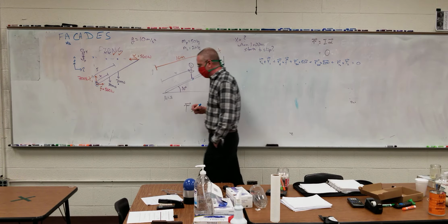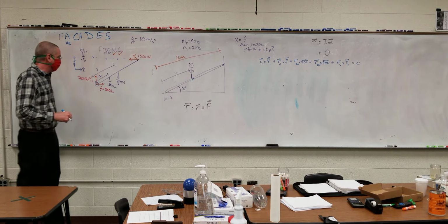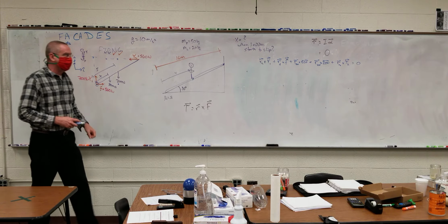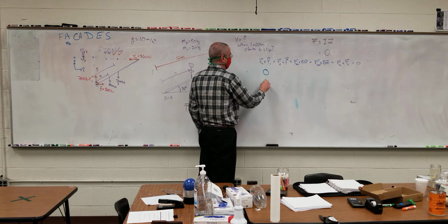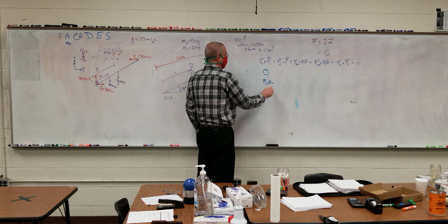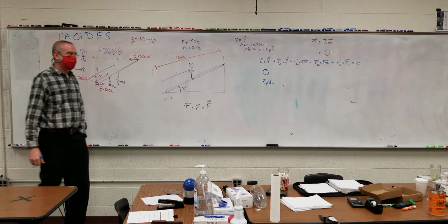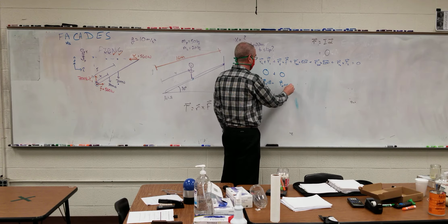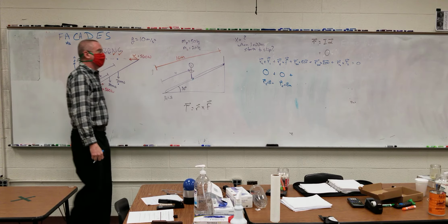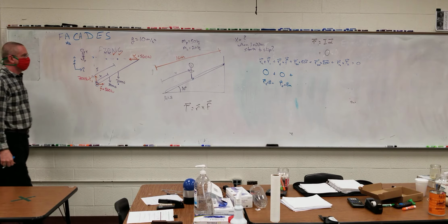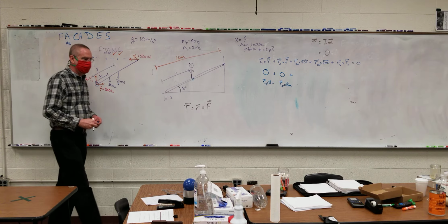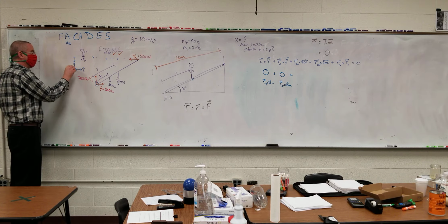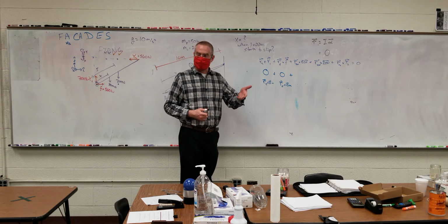And again, this R vector, the moment arm, is a vector from my pivot point to where the forces are applied. So here's my pivot point, and R Y1 is 0 because this force goes straight through it. That's 0 because R Y1 equals 0. Plus 0 because the moment arm from the pivot point to the friction is 0. So we set up our coordinate system with i hat, j hat like this. K hat is coming out of the board. We did an i hat equation and a j hat equation; this is my k hat equation.